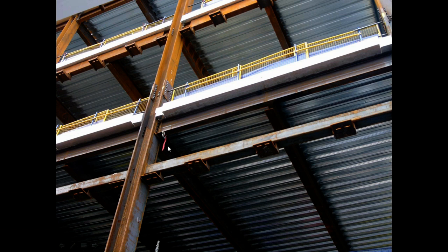Okay. Again, here's a hierarchy of construction. This is an I-beam column. In this case, it's square section, unlike these girders, which are I-beams, which have got a longer flange, haven't they? Because we know that they're spanning, so there's a span to depth ratio. That's the primary structure. These are connecting through to that, and so there's again always a hierarchy of structure.